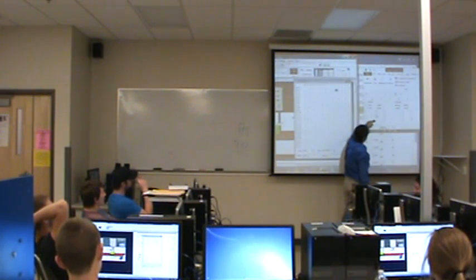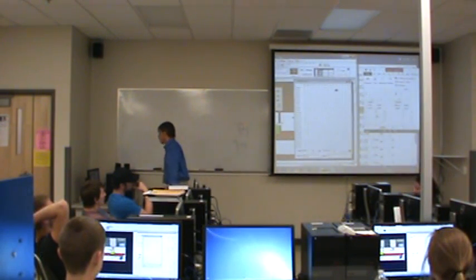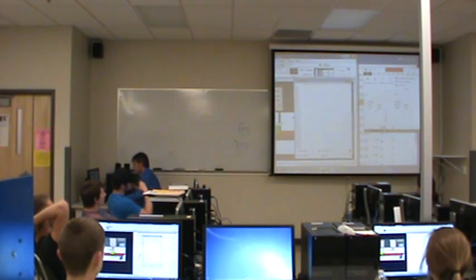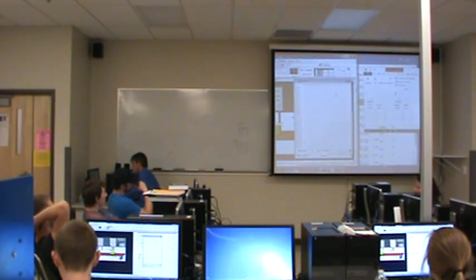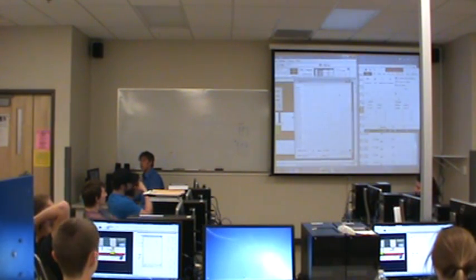So I need 3 ones on address 3 after this. So that's going to look like the following. 1, 1, 1, 1. All I did was I copied this line in here, starting at address 1. Now I'm going to copy this line in on bit 4, starting at address 1. So I need 0, 0, 1, 0. And that's it. My inputs pattern is done.